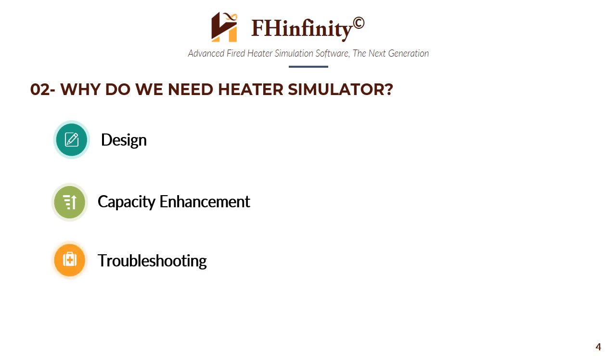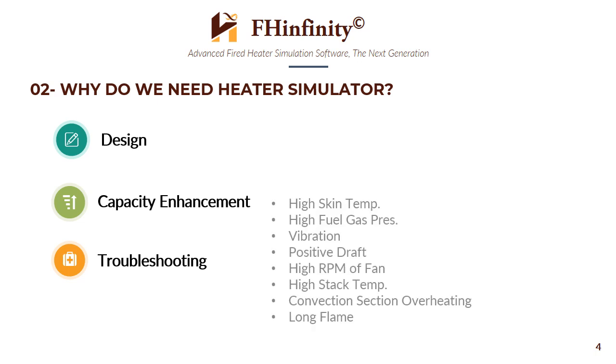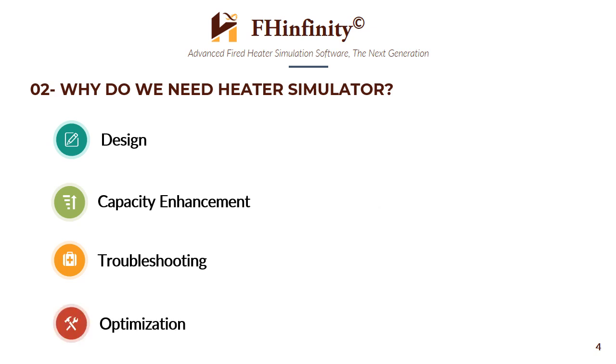Third, operational troubleshooting. When things go wrong in the field, you need answers fast. Are you seeing high skin temperatures? Is the fuel gas pressure too high? Are you dealing with vibration or positive draft issues? Instead of guessing, a simulator helps you pinpoint the root cause, whether it's a flow imbalance, a burner issue, or a hydraulic bottleneck. And finally, optimization.